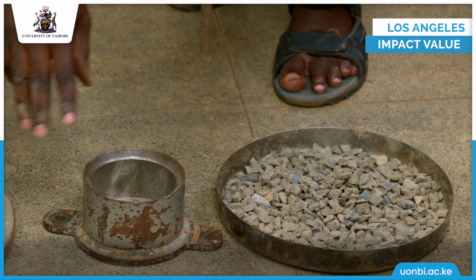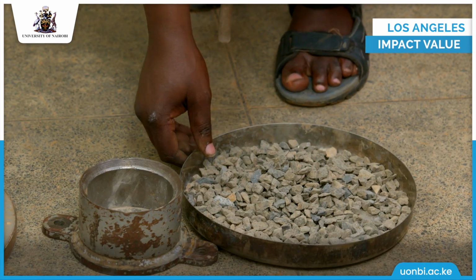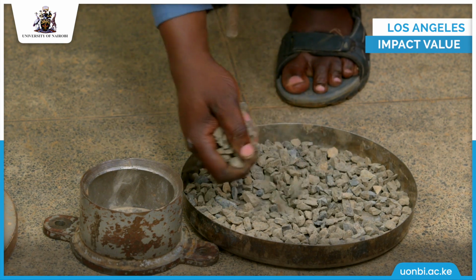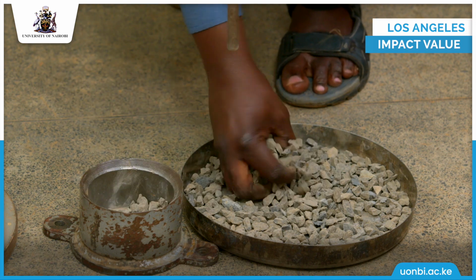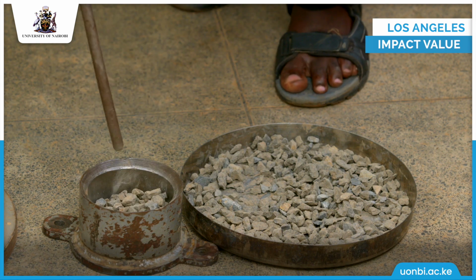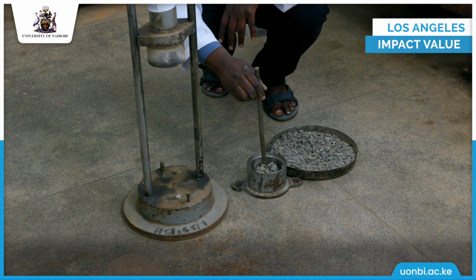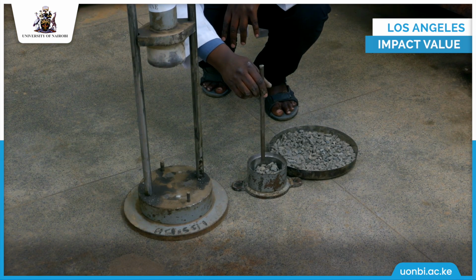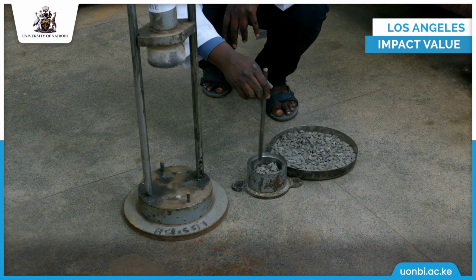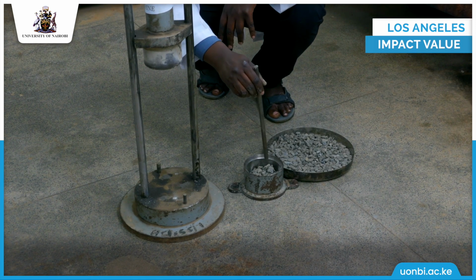We are expected to place our sample in 3 layers. The first layer is a third, the second layer 2/3, and then the final layer. Now, using the standard tamping rod, the height of fall should be 50 millimeters. And we should compact, staggering the tamping rod over the whole of the sample surface.